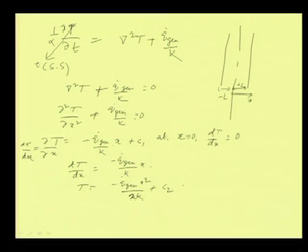Again we have to put another boundary condition: at x equal to L, T equals Tw, the wall temperature. So, Tw is equal to minus q dot gen into L square by 2k plus C2.